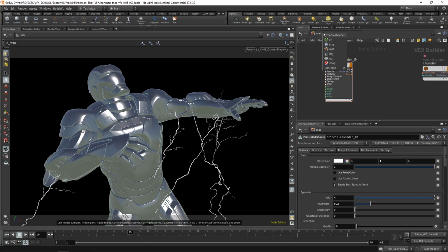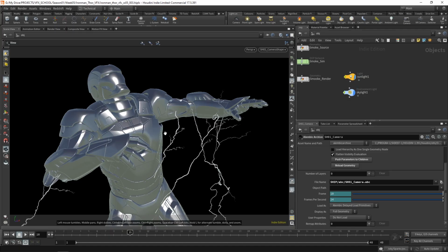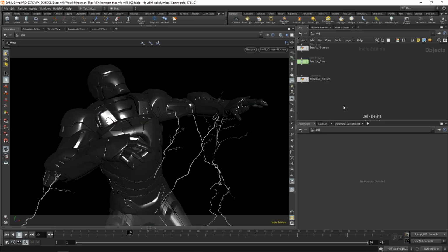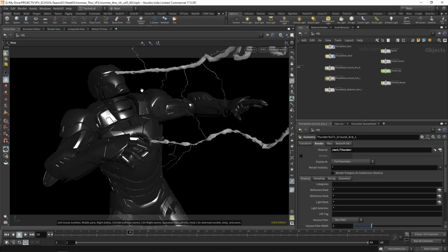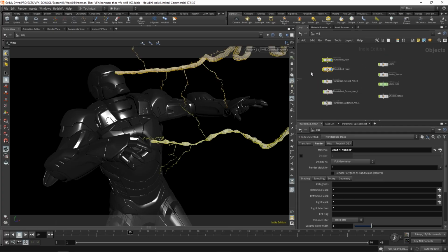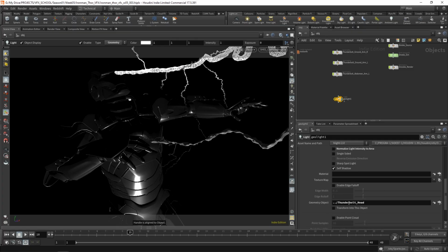It's fine. Going to the objects folder, there are a couple of lights here, the sunlight and the skylight that we use just for visualization purposes, mainly for the smoke. We can delete these. These aren't necessary anymore. So we'll use this geometry as lights. You have several ways of doing this. So let's say we select these two and hit geometry light. This is one way of doing it. So now we should have a geometry light that includes the first object that was selected.